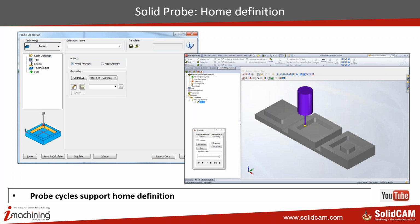For example, for a simple block, you put it onto your vise, you have a stopper at the very end, and you put it up against the stopper, and sometimes that's enough. So all you really need is the very first setup, and then you put it in your home position in your controller, and that's it. You don't have to use your probe again. But sometimes that's not enough.